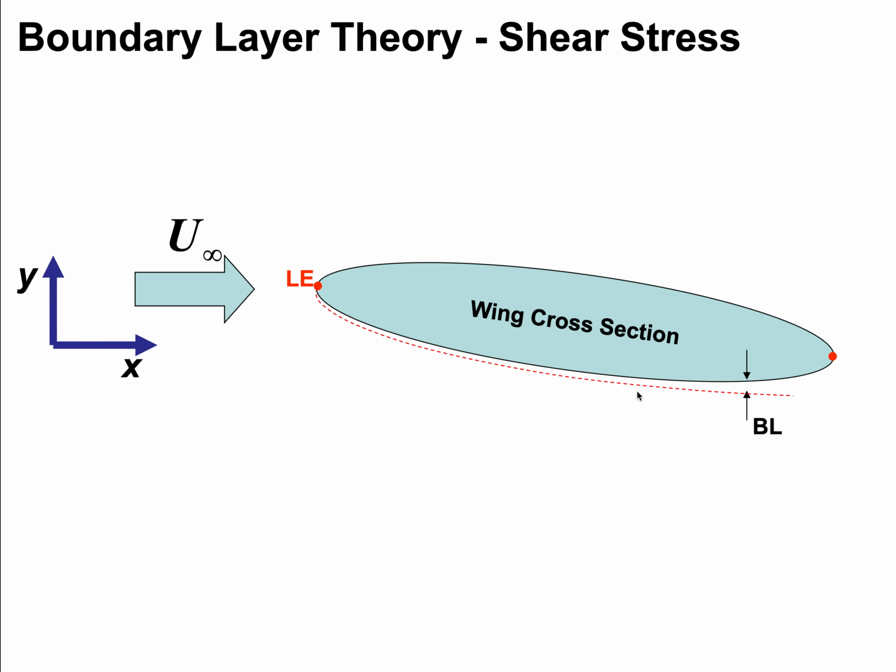but you can see implications of that, in terms of you can measure this boundary layer, and it's a region where viscosity is concentrated. We'll come back to this later on, so don't worry about it. But the primary reason why you have a boundary layer is the no-slip condition. So right on the surface of the object that is going through a fluid that is a gas or a liquid,